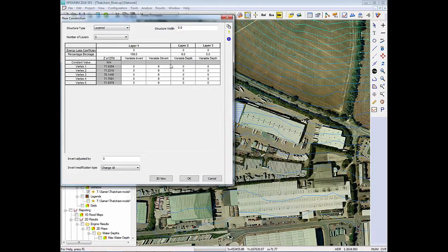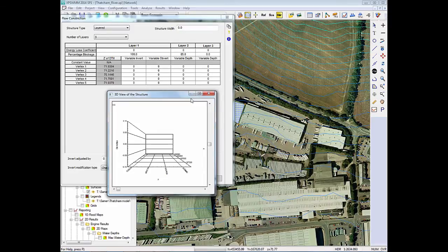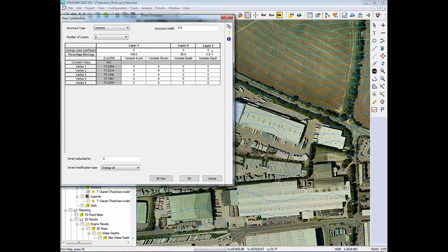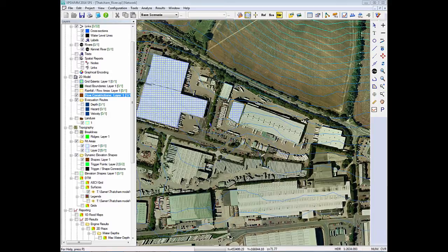According to your openings, you will detect the percentage of blockage, and let's say it's 85. Then you enter the loss coefficient as well. And then from the roof and higher than the roof, you have no blockage. So you have 0% blockage and 0 loss coefficient. By doing that, you're accurately modeling the physical reality.